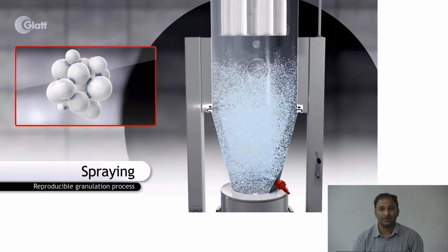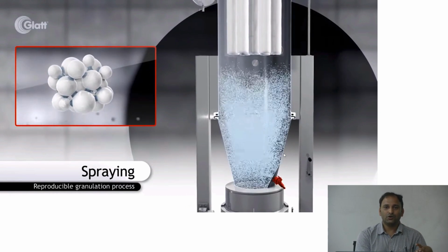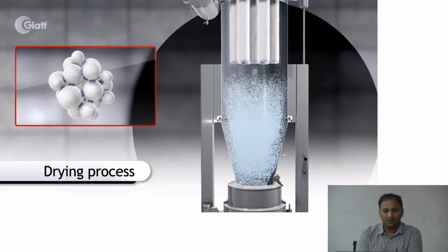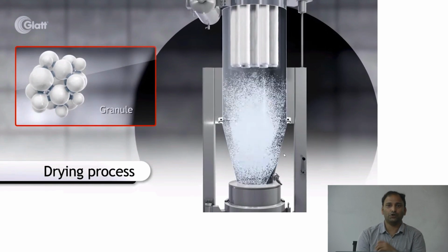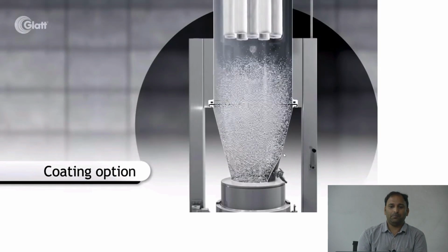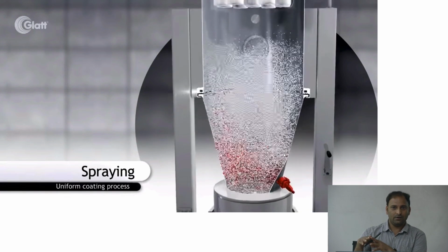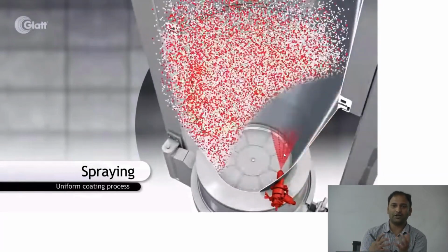It's a process called granulation. That means you start with smaller particles and then you induce some sort of aggregation between the particles. Fluidized beds are used for granulation purposes. You have a packed bed to start with, and then you introduce some gas, and then introduce some way of joining the particles.